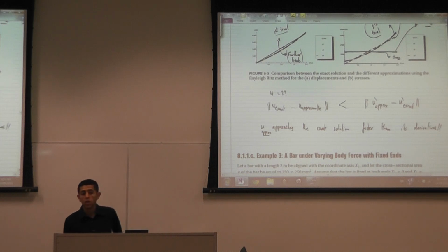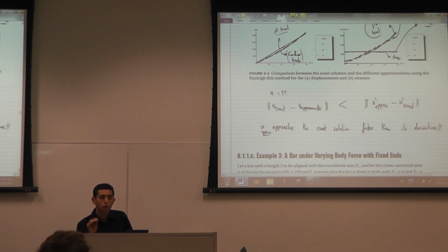And when we look at the finite element analysis softwares, all of them, and I will show you this when we go through software, the finite element analysis softwares hide this fact from you. They hide this fact from you when you plot the contours of the stresses. They always give you very nice contours, but they are actually using a lot of smoothing.